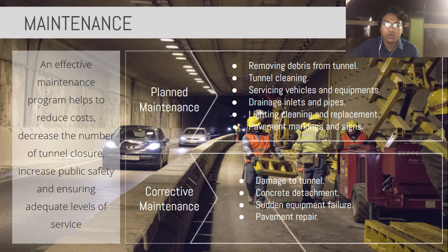Point number 2 is concrete detachment. Concrete can loosen and detach because of faulty placement technique, corrosion of rebar, damage from excessive heat, impact from vehicles and deterioration. And this process may occur without warning. When concrete debris is discovered in the roadway portion of the tunnel, it should be cleaned up immediately.